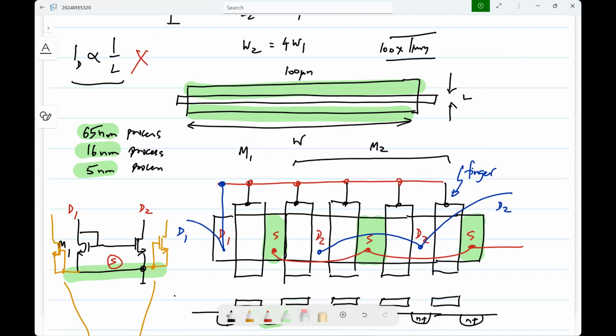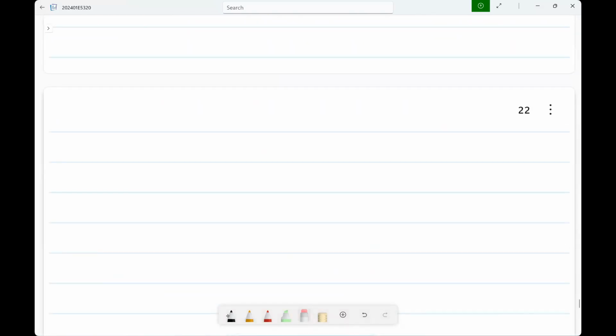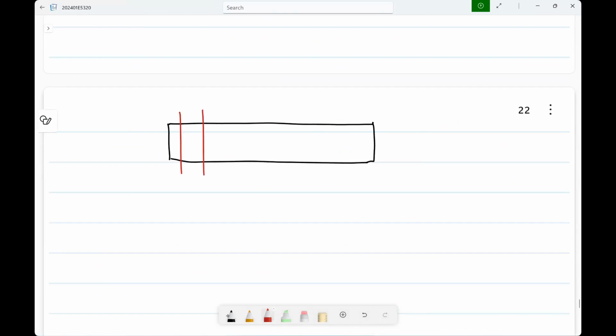By the way, when you are doing design and layout, it always helps to plan it out on paper. When you do that, you can't make those elaborate drawings of MOS transistors. You can make stick figures to see. I mean, let's say you want to explore different types of connections. These correspond to the gates. And maybe you have a different transistor. You can try out different things.